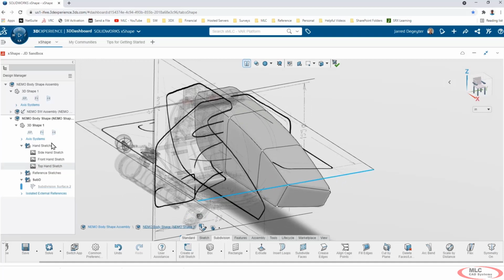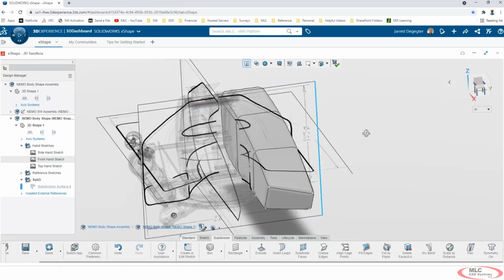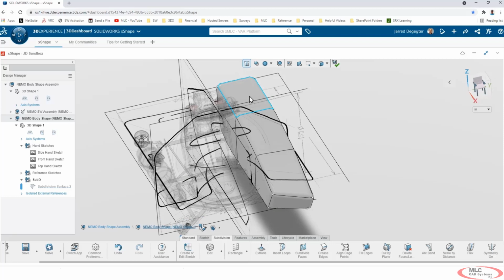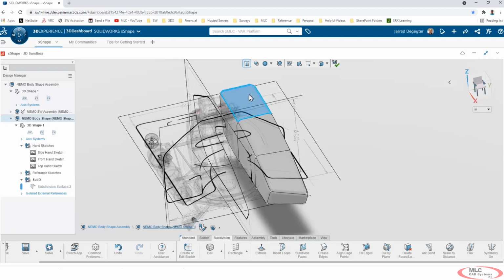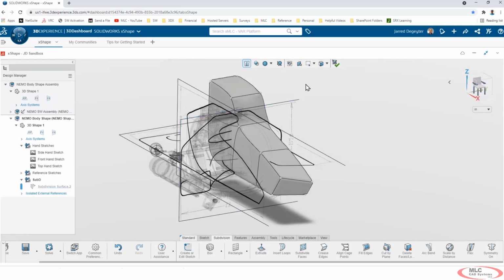All right, now one of the things that I'm sure a lot of folks do whenever they're modeling something up in SolidWorks or any other CAD platform for that matter is maintain symmetry, right? And we can definitely do that. Before I show you guys the symmetry command here, though, I'll add a little bit more virtual clay onto that top face. We can do that from the context toolbar. It's just a simple pick, and then it just slaps some additional virtual clay to work with, just like that.